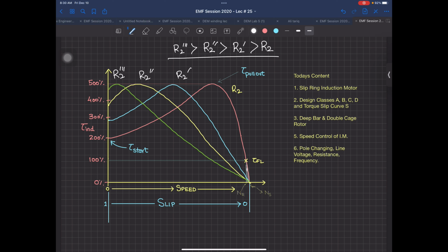So practically they have an induction machine in their car, and they have three motors actually. Two are in the rear, one is in the front of their tires. So practically what I think, how they are actually achieving it, because they need a rightful acceleration at the start. So maybe their rotor is not based on this resistance, because when you have a resistance using carbon brushes, you are going to have a lot of efficiency issues. So practically this is not the solution which they are doing.